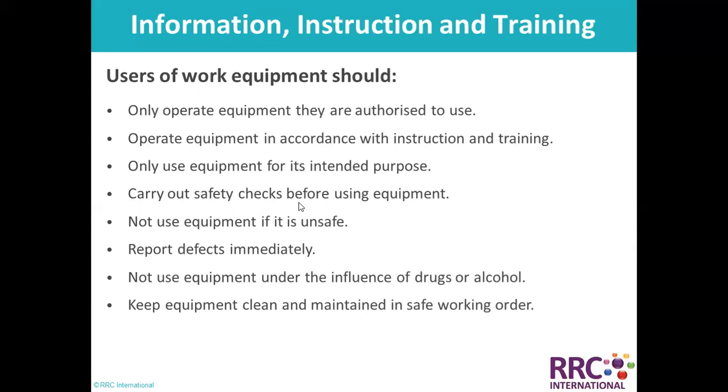Before using anything, they'll surely be checking; they must have safety checks, a kind of pre-use inspection checklist for everything, including tools, equipment, even rigging and lifting gear. Do not use equipment if it is unsafe, and report defects immediately. Do not use equipment under the influence of drugs or alcohol, because it's illegal also, especially in Saudi Arabia. Keep equipment clean and maintained in safe working order.